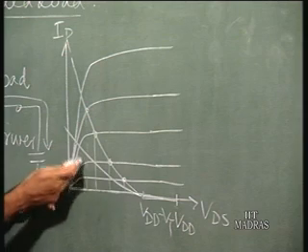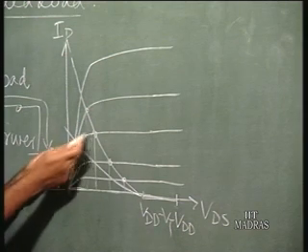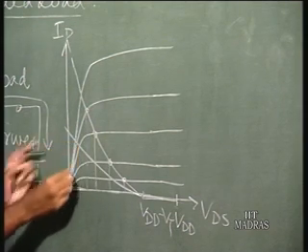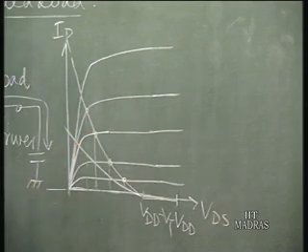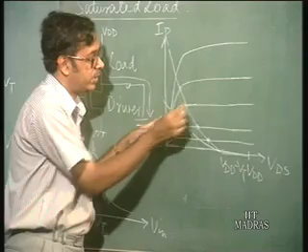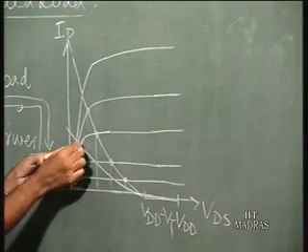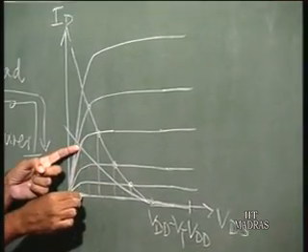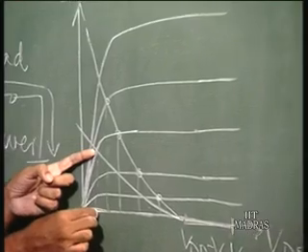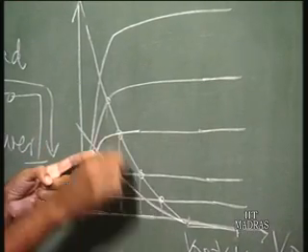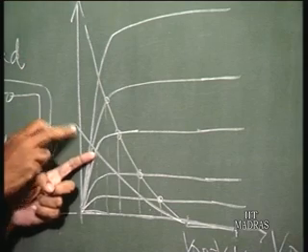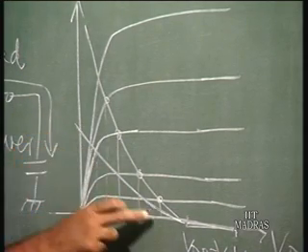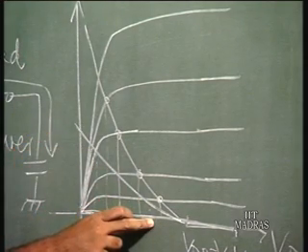See, for the same gate voltage, say the input voltage is somewhere here, it starts falling from V in equal to VT, but for the same input voltage here the output has fallen to a lower value. For this, if the load line was like this, it is still at a higher value. So, obviously for this curve the gain is more.